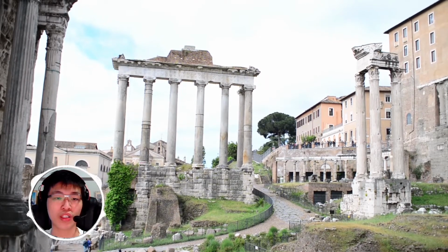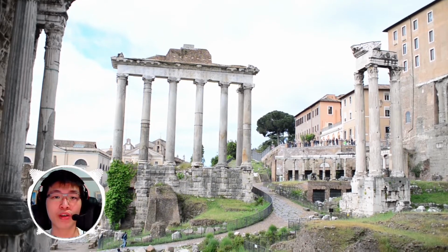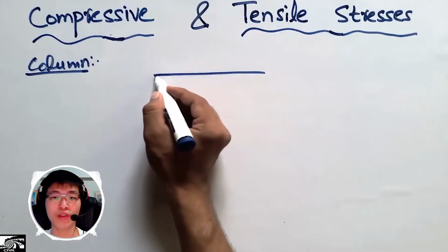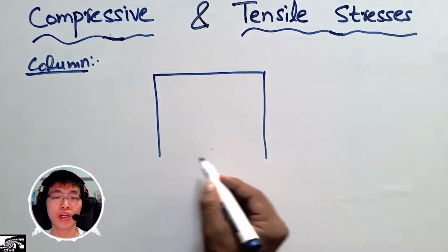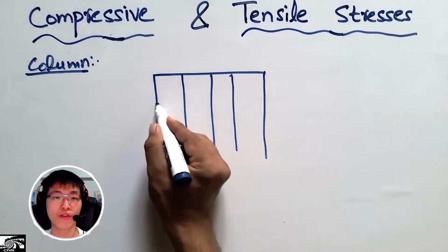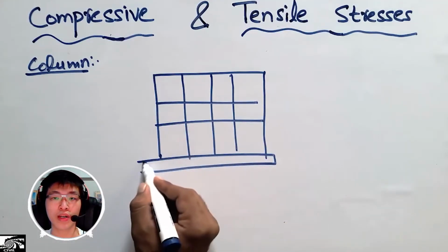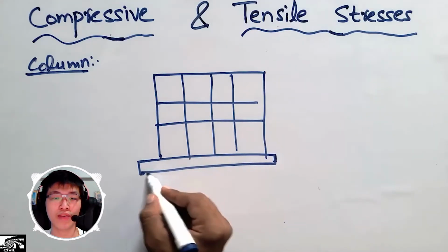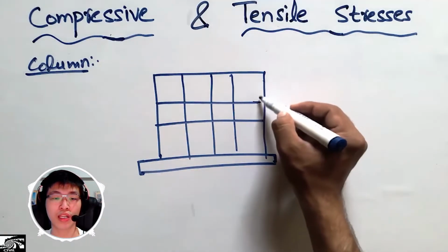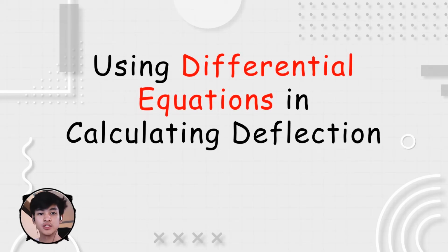Beams and columns deflection is the bending of the component due to applied loads. The bending of a beam or columns occurs when the compressive load of the component reaches its critical value. The main causes of beam and columns deflection are wind load, shear load, uniformly distributed loads, and point loads. Failure to compute the deflection properly can result in serious deformation and damages, as components will tilt and collide. In relation to that, the calculation of bending moments require engineers to have profound knowledge on differential equations, as this is the basis for derivations.